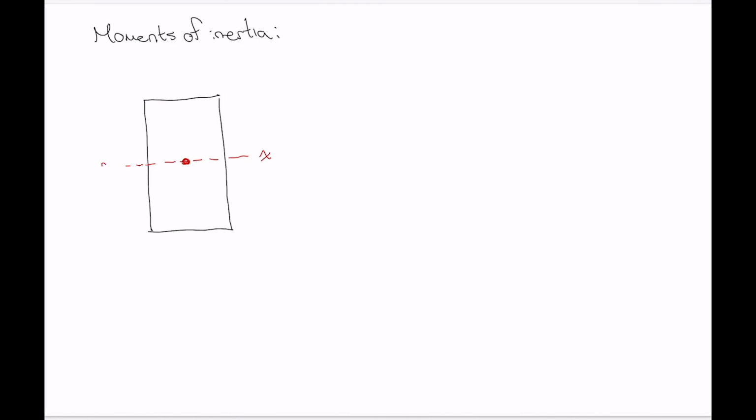We see rectangles, things with rectangular cross-section, a lot. Here's our horizontal x-x axis. Here's our vertical y-y axis. And let's say our cross-section has some sort of width W and some sort of height H. The moment of inertia for a rectangle is 1/12 base times height cubed.